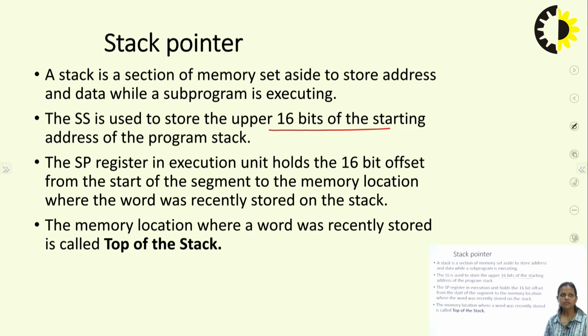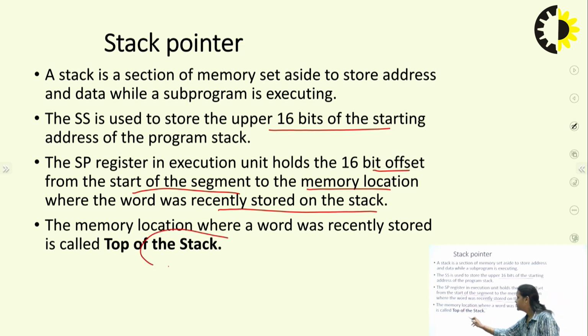The stack pointer register in the execution unit holds the 16-bit offset from the start of the segment to the memory location where a word was recently stored on the stack. So again, the stack pointer register holds the offset address. The memory location where the word was recently stored is called the top of the stack.